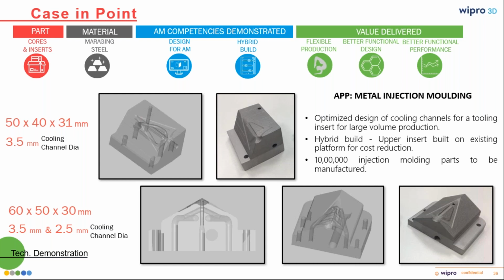And again, DMLS comes out in favor because the surface finish is relatively on the higher side, and for mechanical properties, the kind of hardness that we want is somewhere in the range of 60-62 HRC when we are working with maraging steel. So it requires to be heat treated, but again DMLS comes out in favor with these kinds of parts. And interestingly, we can incorporate this with machining. Sections which do not require those complex designs can be conventionally manufactured and fixed on the base plate, and only the section having those complex, curved cooling channels can be 3D printed.